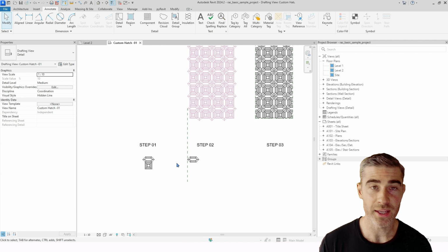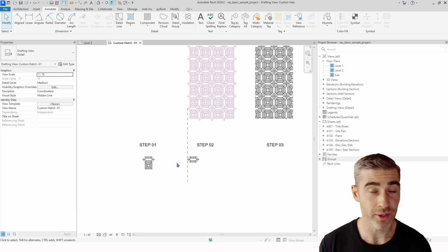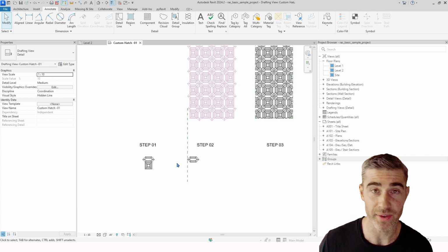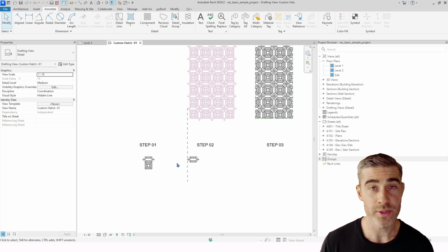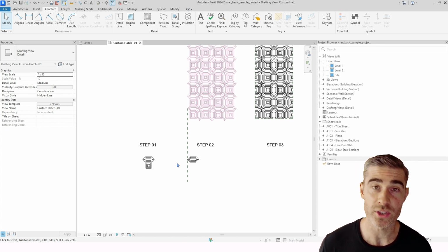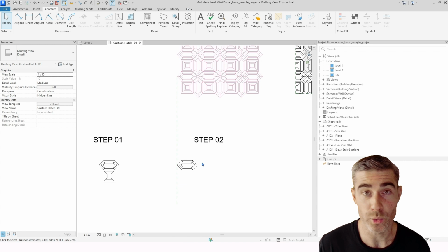At this stage, there's so many different ways you can do this. You can just use detail lines for the entire sketch, and that's fine. You can create a group. You can then copy them to wherever it's going to happen, or you can use the array command. Whatever is the most efficient to you is absolutely fine. For today's exercise, the most efficient way for me is to array these.